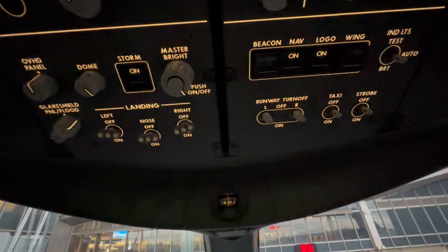The little switch on the upper left corner, which says indication light test, that's an interesting one. It's got 3 settings: test, auto, and bright. When you put it to test mode, all the lights within the flight deck go to bright for 10 seconds, then dim for 20 seconds. When it's on auto, the computer, the CCR, Common Computing Resource Software, will basically auto adjust the lighting system. Then bright is bright.